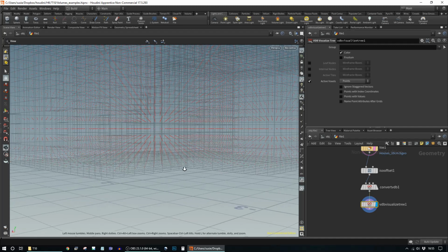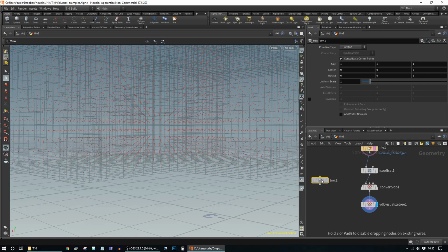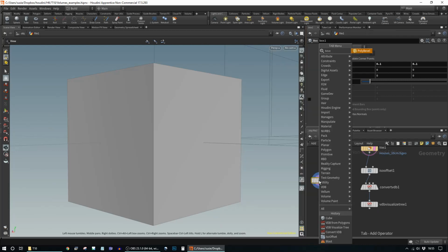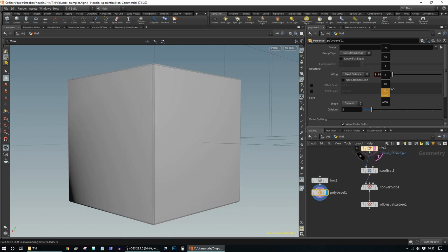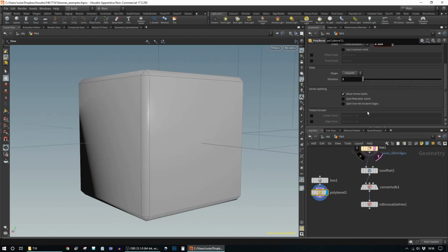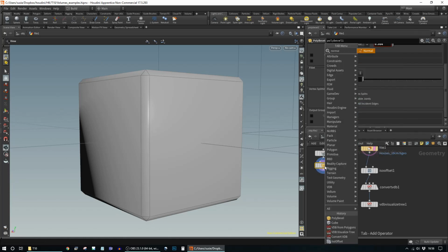And then all you need to do is replace these. So I'm going to create another cube, and again we'll make it 0.1. Make it a little bit interesting by beveling it. We've got very simple bevels, and I think probably fix the normals on that as well before we do anything with it.